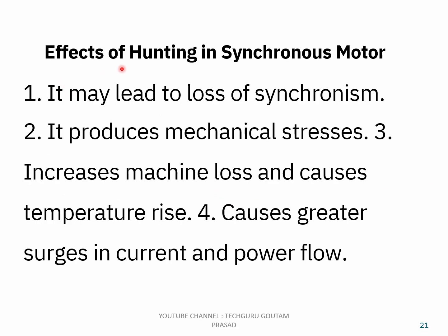So the effects of hunting in the synchronous motor are as follows. It may lead to the loss of synchronism. That means the synchronous motor will go out of synchronism and it might stop or stall altogether. Second, it produces mechanical stresses on bearings, on windings, on whatever mechanical components you have in the motor.